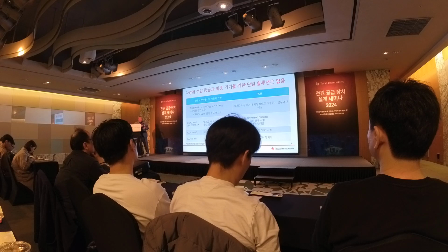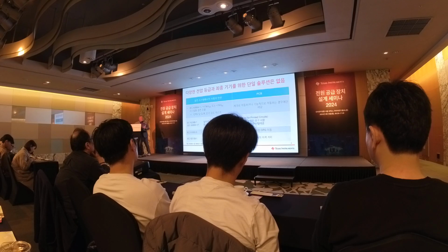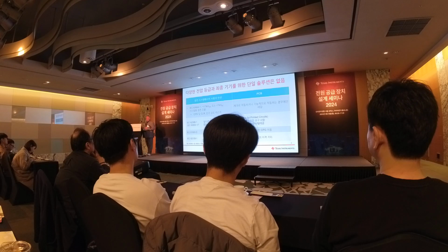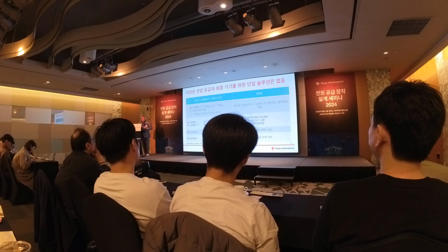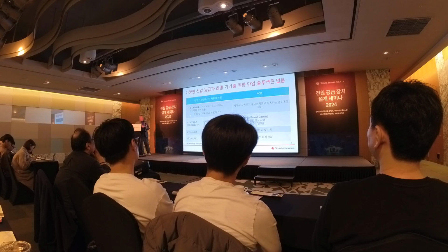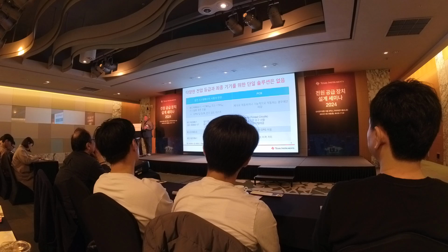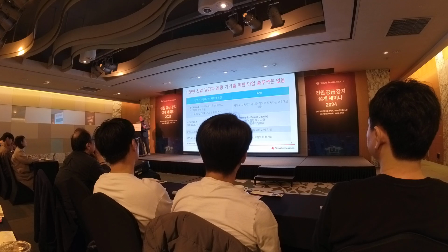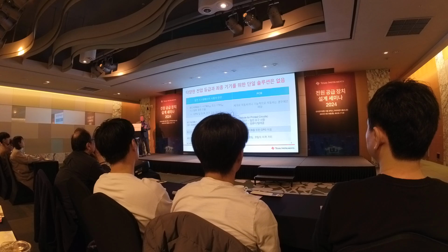So there are a huge number of IEC standards, and every end equipment basically has its own standard. So we've shown a few here. IEC 60664 is the first one, and this is the most common one in which creepage and clearance are actually defined. It's a standard one that's used if you don't have another special one for your given end equipment. If the end equipment that you're working on is telecom, server, audio, communication equipment, then you need to use this standard,